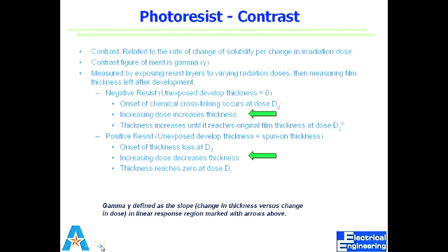So now if you think about it, if the resist has to change from bottom up, you get much better contrast than if you start from the top down. And this comes from the slope of the sidewall that we get at the end of the exposure.